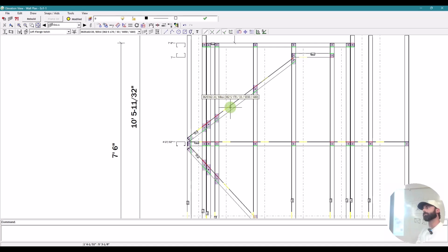Because if you could see all of the material that's being removed out of this brace, that's a vulnerable point for production. So the first thing out of the machine is stud 1, and then brace 2, and then as it's finishing stud 1, the machine's about 12 feet long, so we'll slow that down to like 15-20%, let these braces get out. We could speed it back up as it starts printing top plate, stud 2, and then next thing that'll come out is this jack stud, and that sill.